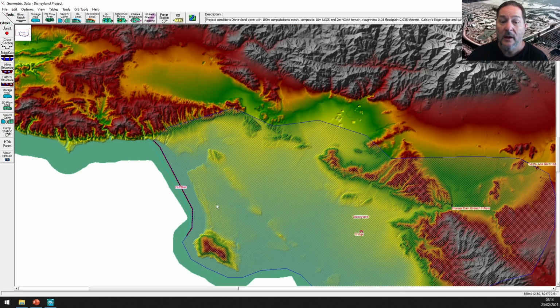But there are cases where the backwater effects from adjustments to the assigned slope here at the outflow boundary condition can propagate for miles and miles and even go all the way through to the other end of the model, depending how flat the rest of your terrain is. So definitely run some sensitivities on that. We'll talk about that in the next part to see how things change.